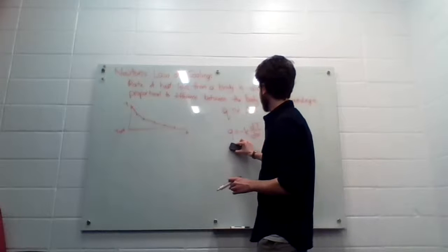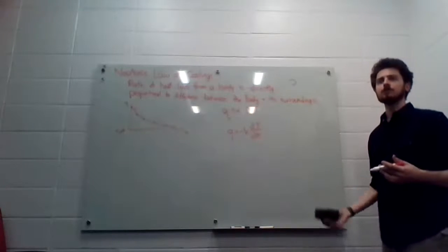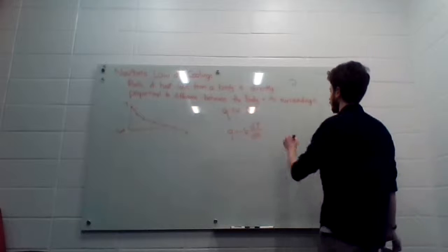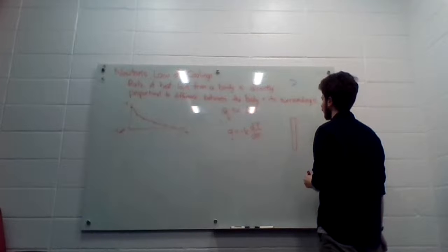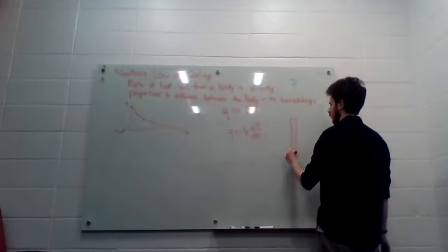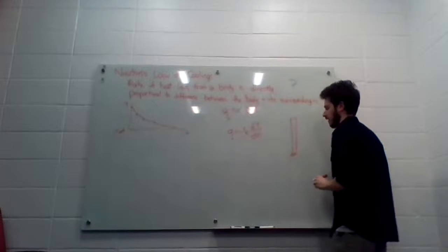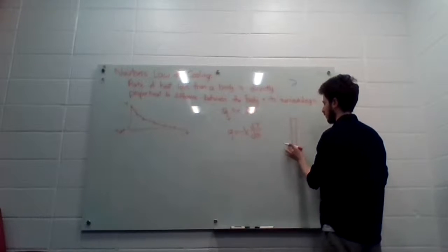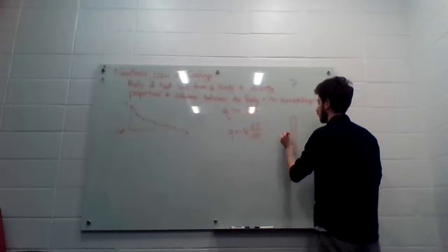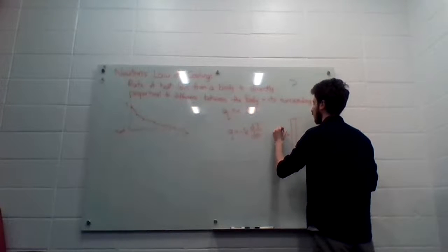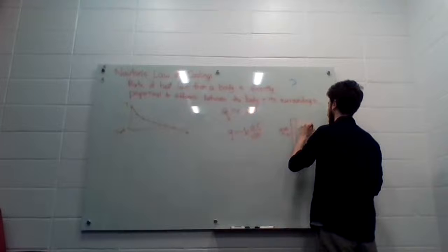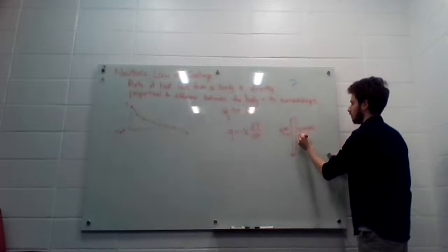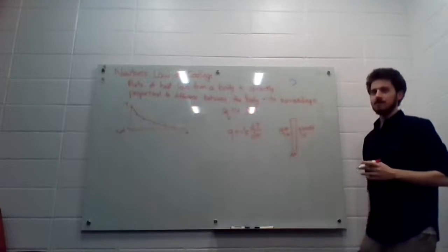So does anybody have an idea, moving from this, we want to develop that heat diffusion equation. Basically the assumption with the heat diffusion equation is, I suppose there are different heat diffusion equations. We're going to assume you've got some kind of simple one-dimensional thing, delta x, some small width slab, and you've got qx here, q evaluated at x plus dx coming out, no internal heat generation there.